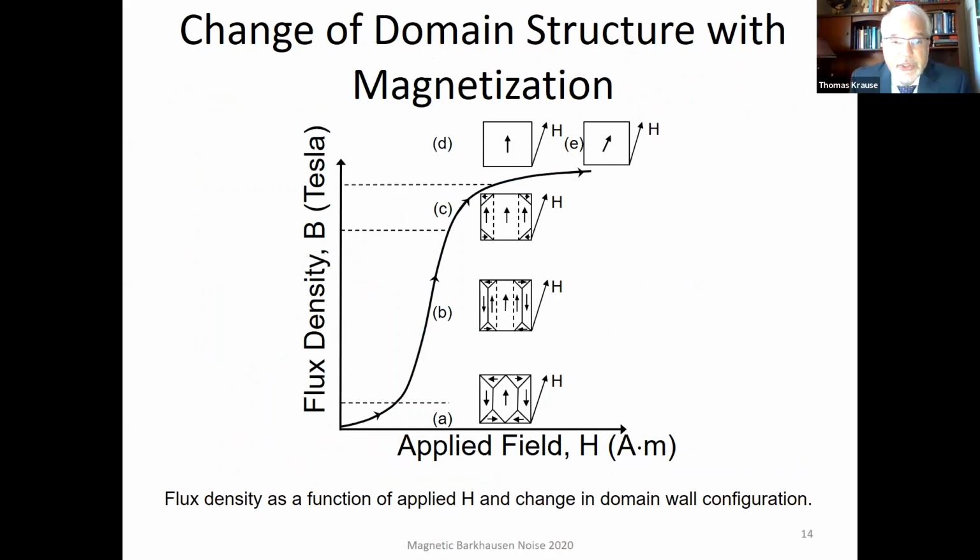So we can relate this to our initial magnetization curve if we were to apply a field to a steel material. Down at the bottom, region A, we're in the Rayleigh region, and we have some reversible processes going on, so we can move 180-degree domain walls very easily.